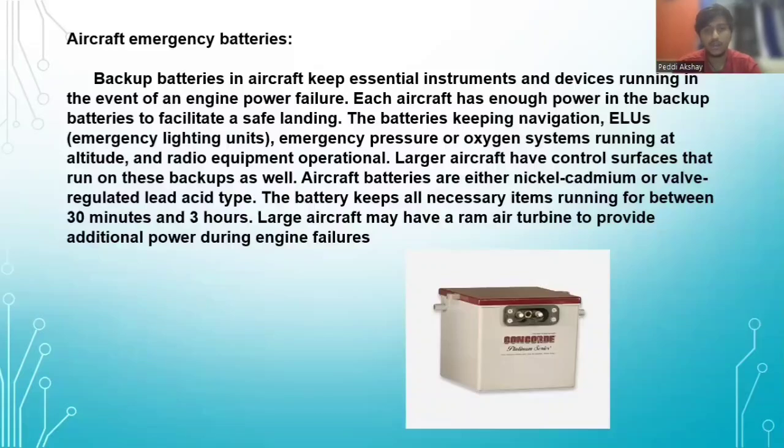Aircraft batteries are either nickel cadmium or valve regulated lead acid type. The battery keeps all necessary items running for between 30 minutes and 3 hours. Large aircraft may have a ram air turbine to provide additional power during engine failures.